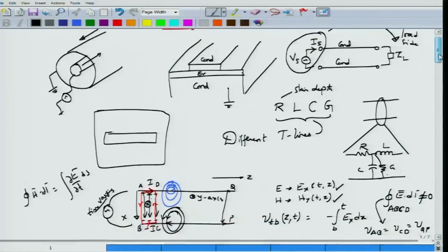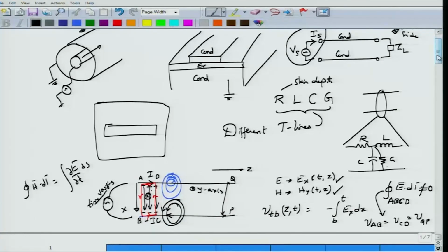transmission line is something that would actually have electric and magnetic fields present because of the time varying potentials and currents present on the transmission line. Most importantly, this Ex and Hy are there on a two wire transmission line, and these are the only two components that you can have, or you can have Ey and Hx depending on how you label the axis. And these Ex and Hy are oriented perpendicular to each other. Further, the wave, or the energy, is actually traveling along the z axis.